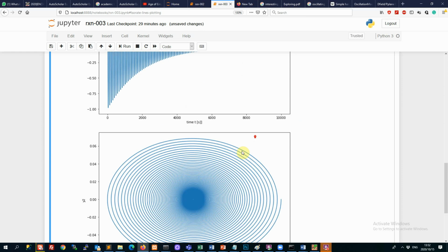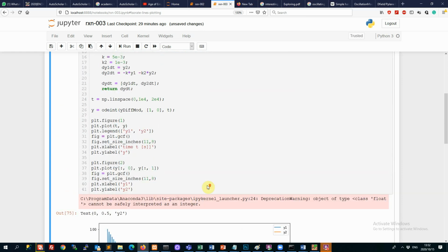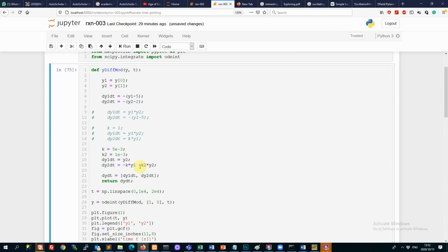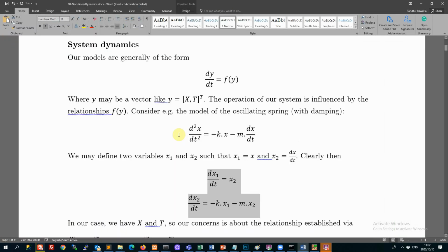So the overshoot is getting smaller and smaller, and eventually it's getting closer and closer to the rest state. So this case does have a steady state. So you have a steady state for particular values of the coefficient here. So this introduces the idea that in your differential equations, the number of steady states available to your system is a function of the parameters that govern that equation. And that's what we'll be exploring in the context of our reactors.